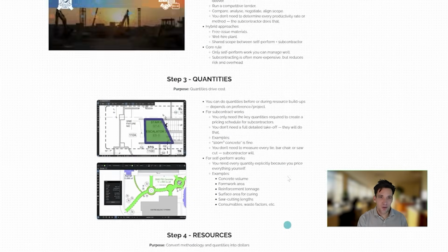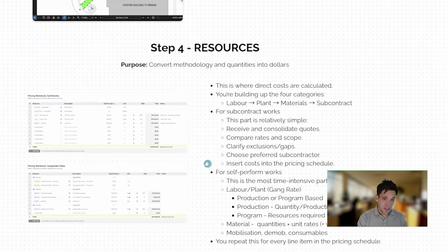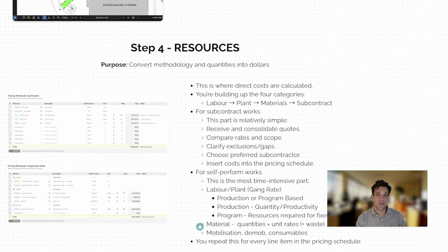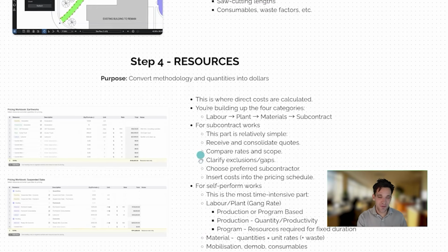And that's all it is. We go through our entire pricing schedule, price every single individual item to come up with our cost. Very basic maths. The hard part is getting all the information together, populating our resource library, getting accurate rates for everything, accurate subcontract quotes, and also understanding the construction methodology. To me, the maths, whatever, is the easy part. The hard part about estimating is getting all this information together.